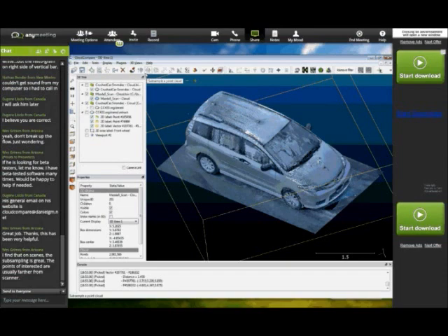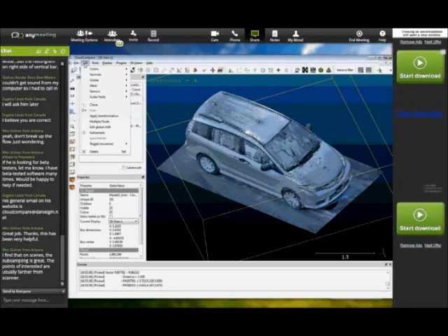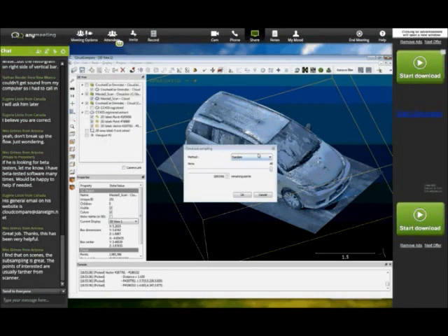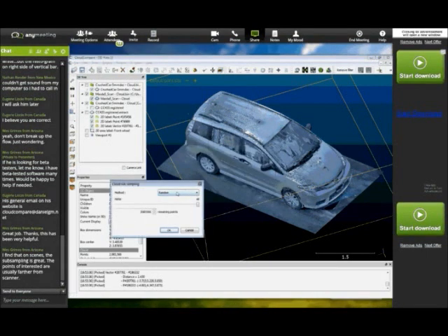Then you have three choices. Either you randomly select a given number of points, quite easy to understand. It won't change, however, the relative differences of density between the points. So what interests you more is the space method, which will guarantee that you won't have two points closer than the length that you define here.